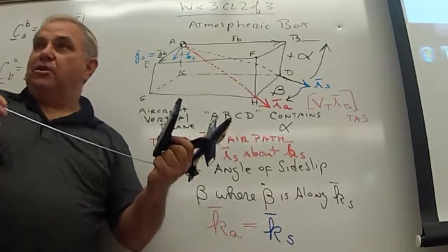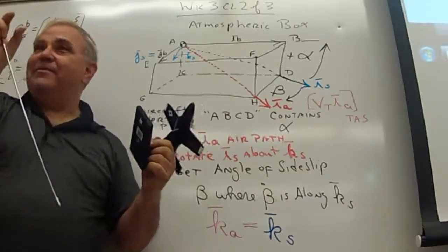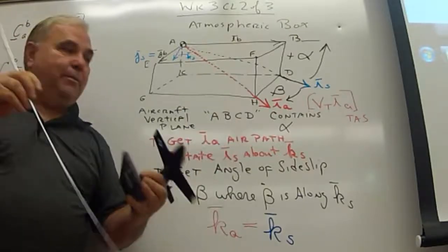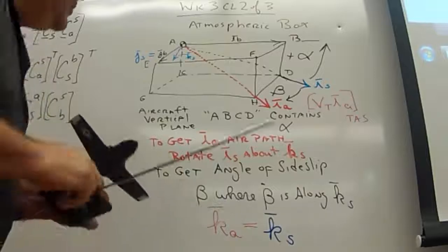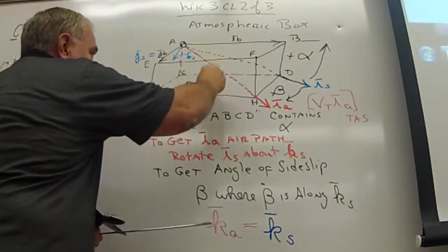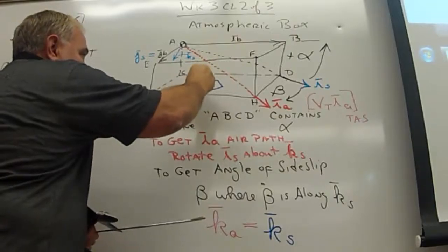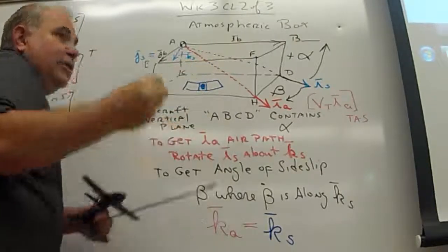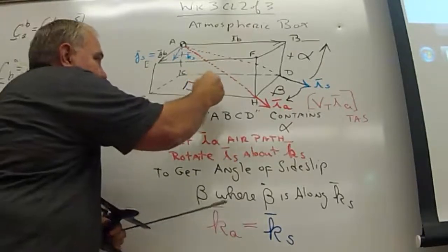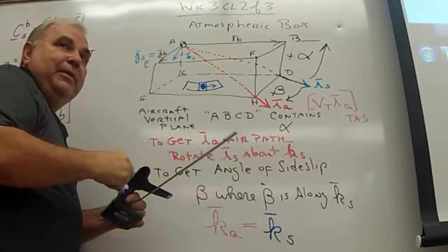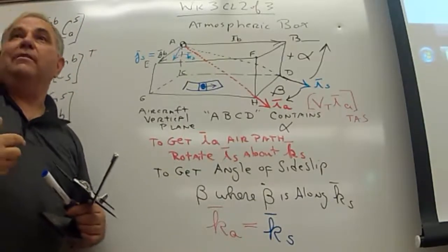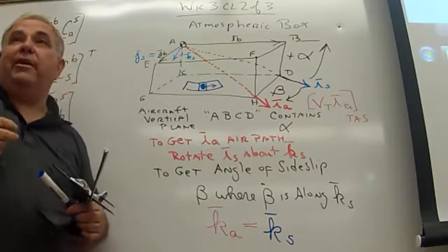You see that? There's a ball in the race. Right? There's a little ball, and then you're taught to step on the ball, right? So you have a little ball that's in a race, this is what it looks like in the airplane. I'll take a picture of it like this, and the ball sits right in there. And you can think of yourself as the ball, right? As yourself. So if that ball moves like over here, that means that you should feel your right shoulder being pushed against the right door. And that's because the lift vector isn't right over your head.